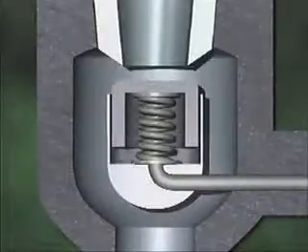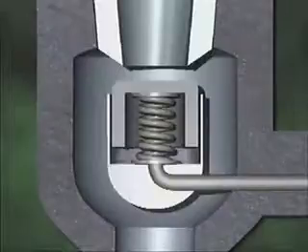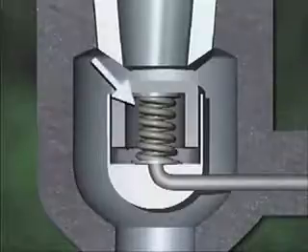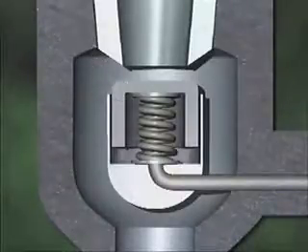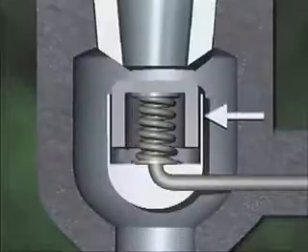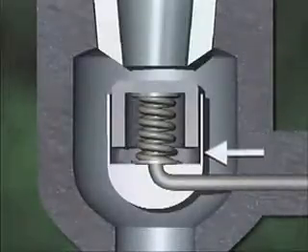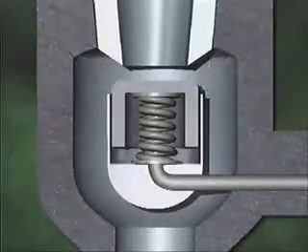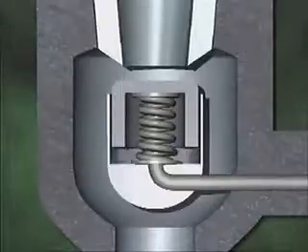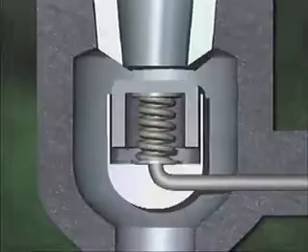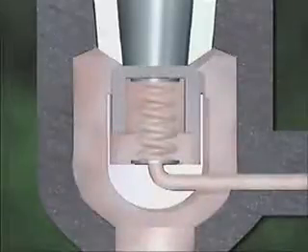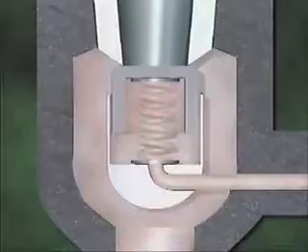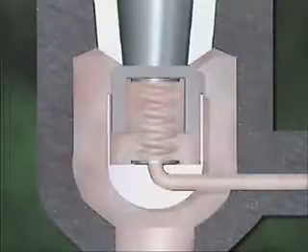The disc opens downward, allowing the steam to escape through the outlet at the upper part of the valve body. Also, in this example, the spring is placed below the disc. The valve also has a disc guide, which is a sleeve that aligns the disc with the seat. A small opening between the disc guide and the disc allows system fluid to pass through from the inlet to the bottom of the main disc. Consequently, system pressure is exerted on both the top and the bottom of the disc during normal system operation. Spring tension is also exerted on the bottom of the disc.